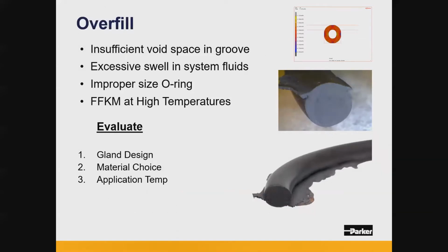And I will also note that excessive swell can be something that causes overfill. So overfill, I guess, can be considered design, and it also can be a result of material selection, but excessive swell on system fluids, so make sure you have that in consideration. And then also the temperature of the application. As elastomers get heated up, they will swell from thermal expansion. So you need to make sure, especially in high temperature applications, that you have considered that impact for your allowable groove space.